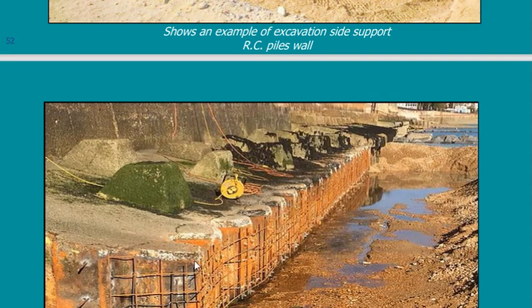How can this happen? They just covered the face of the shoring system with reinforcement, and they are going to use concrete, shotcrete. They are going to cover the face of these piles instead of having bubbles of piles. It will be finally a smooth retaining wall, as if it was a retaining wall that was constructed.